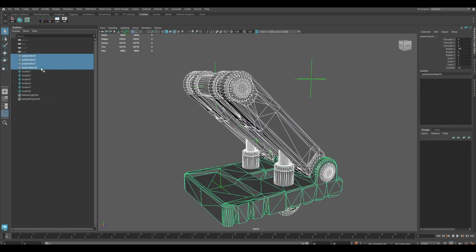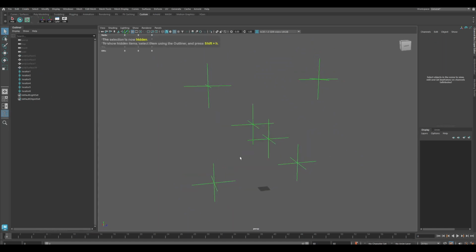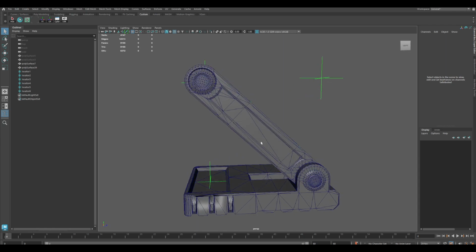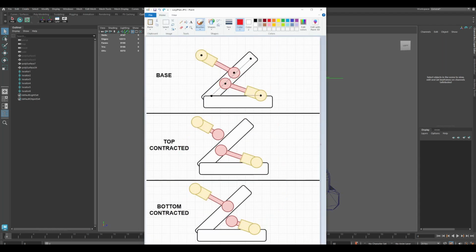Now let's continue with the creation of our skeleton. In Blender this will be called Armature. Let's show these parts to explain what we're going to do. We're going to create these parts here. So these arms of our skeleton will control the movement of our top and bottom part of the landing gear. So we'll have one root bone where our coordinate system starts. Then one bone will start here for the top part of our landing gear. One bone for the bottom one that will start here and end on the tip of our bottom part. Our skeleton will look like this.